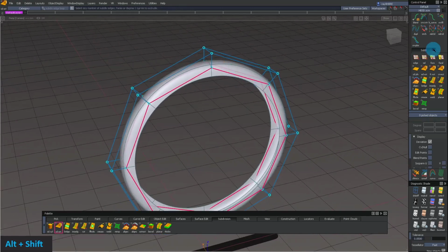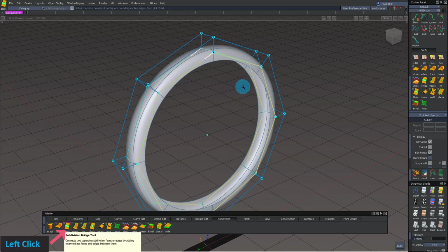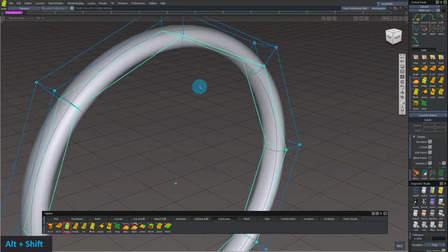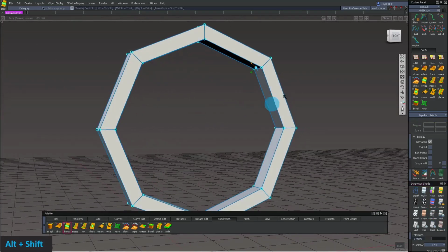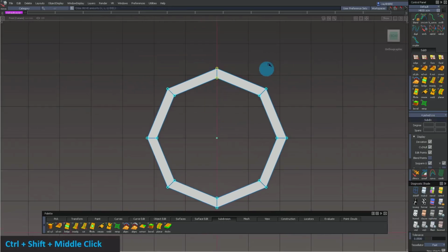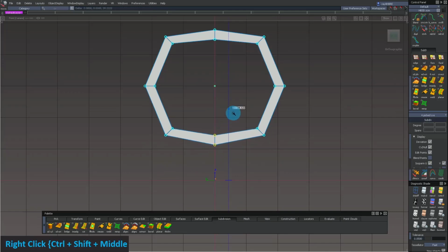And now we want to connect the bottom edges. So I'm going to select both of the loops again. And now I'm going to use the bridge tool to bridge between those two loops and close this up and make it into a torus, which is already in our standard primitives. But this way you could see the different tools and get used to these different little concepts. So now we could actually move the CVs around to make the steering wheel a little flatter.